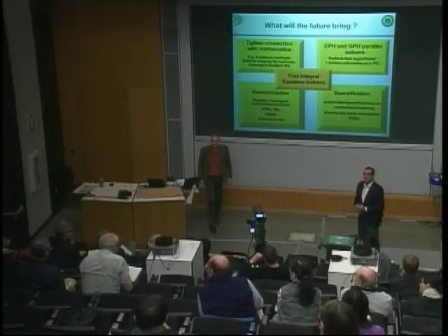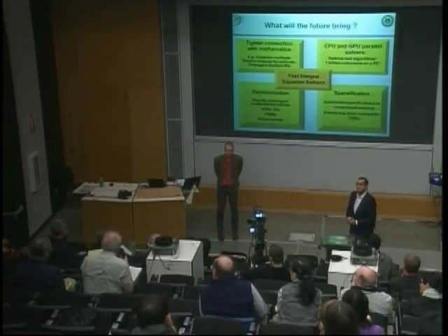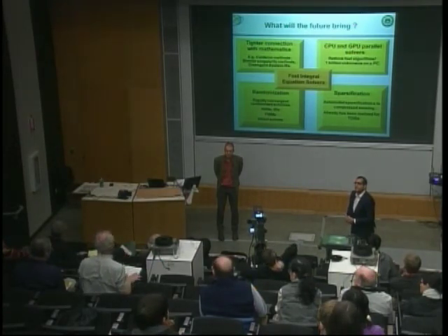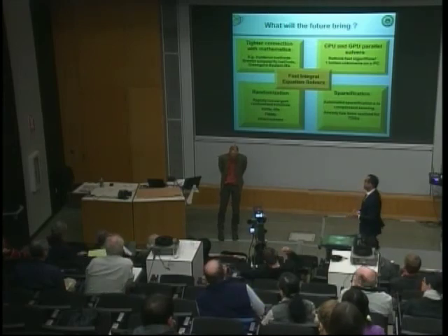I'm curious about your time domain integral equation. If you want to analyze very low frequencies, how long response times do you have to do that? It's important to realize that when we determine our time step for these solvers, the time step is not determined by the edge length in the mesh, as it is when you do, say, a finite difference solver. These solvers are implicit.